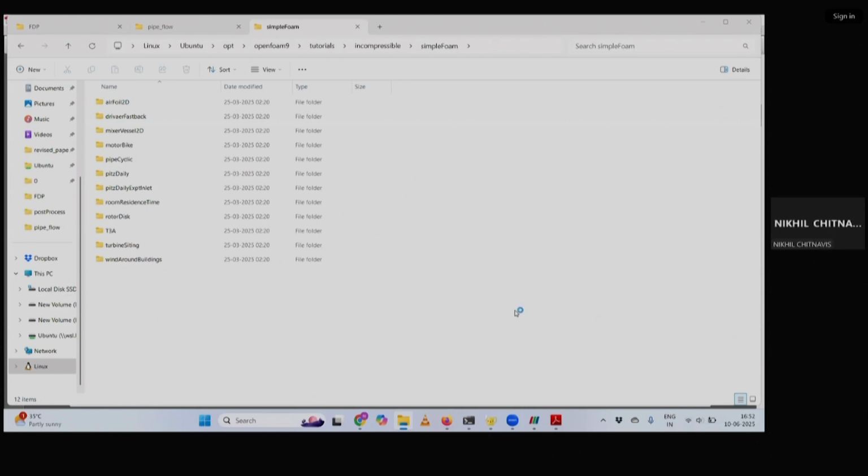Using that CAD file, you want to create a mesh and do the analysis in OpenFOAM only? Okay, if a CAD file is there, there is a meshing tool available in OpenFOAM called snappyHexMesh. cfMesh is also there. Using that, you can use the STL file to create a mesh.